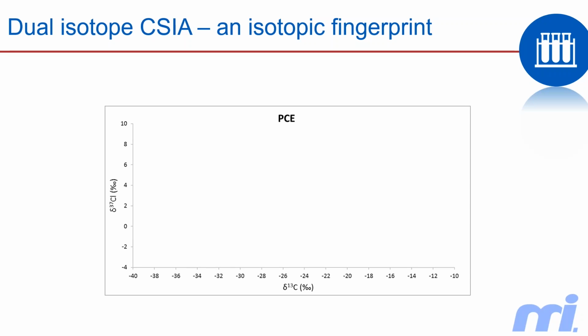So as Dora mentioned, we can use CSIA for many purposes. Generally, the most common use for CSIA in the environmental remediation industry is proving without a doubt that a contaminant is degrading, and that's done by watching those delta values change. As Dora said, we might measure a compound like PCE, so we're measuring distinct compounds.